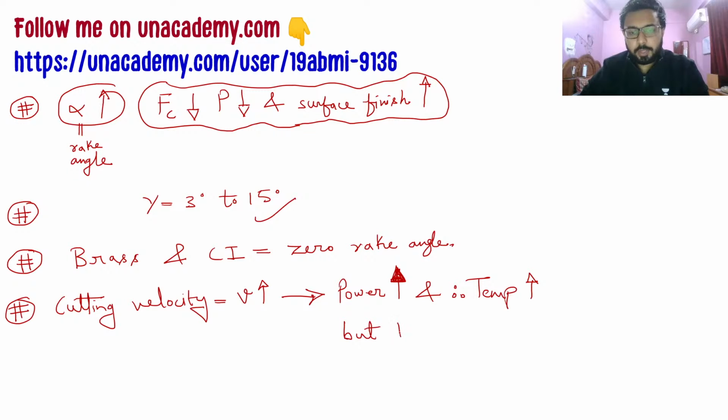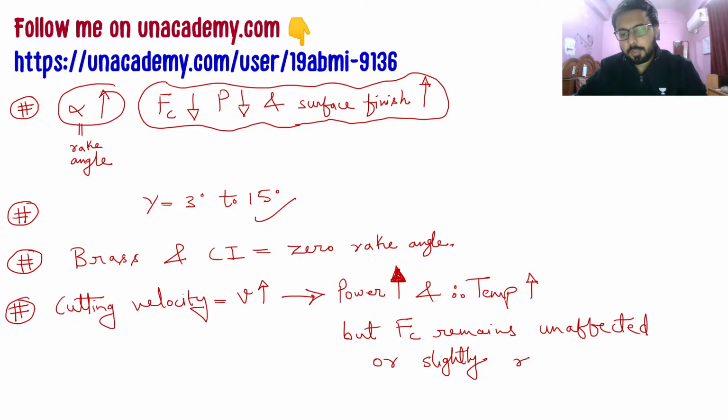But FC remains unaffected or slightly reduced. Why slightly reduced? Because since temperature is increasing, the workpiece will become soft, and due to that the force requirement will decrease. So it is reduced very slightly that we can just neglect it.